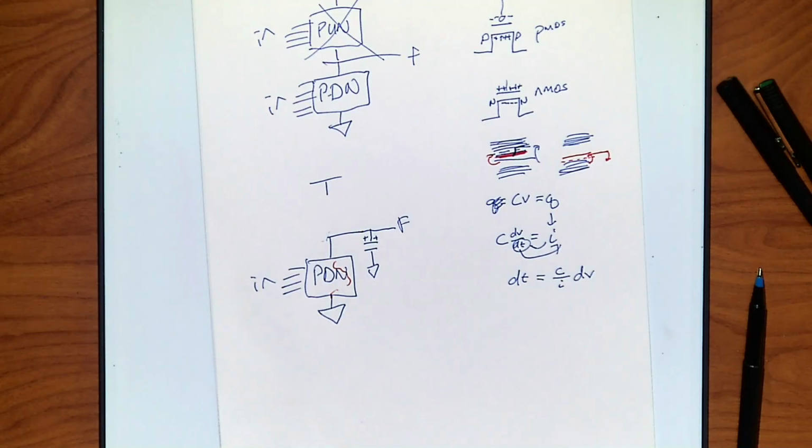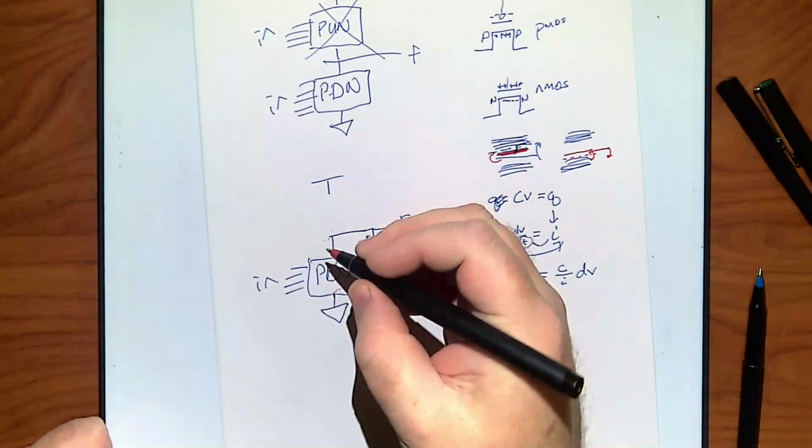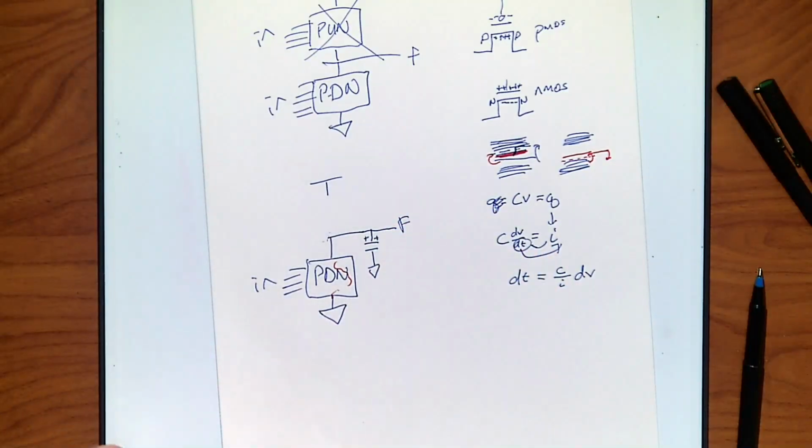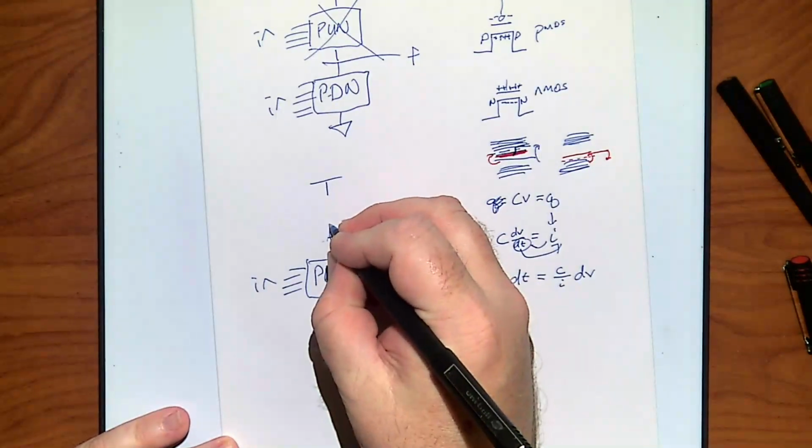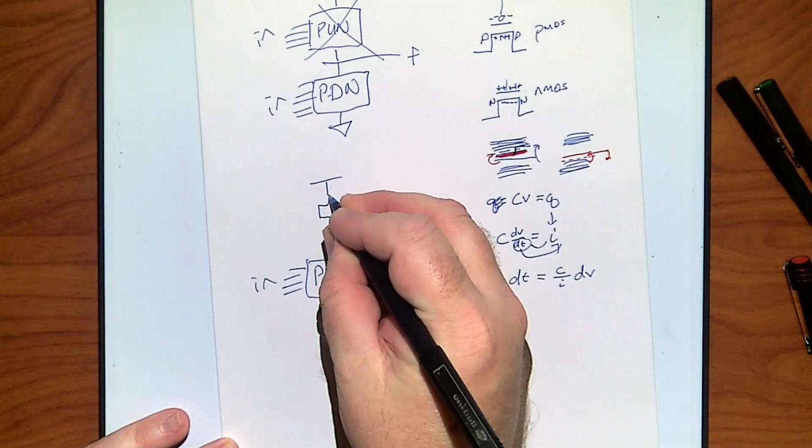You use your clock cycle anyway, just to pull it into storage, to hold it, to get it to the output and ready to go for the next cycle. Does that make sense? So it looks like I'm doing something I hate, but I really don't have a choice. I have to supply power, so what's the only thing that works well to supply power? Yeah, PMOS is the only thing I can do here.